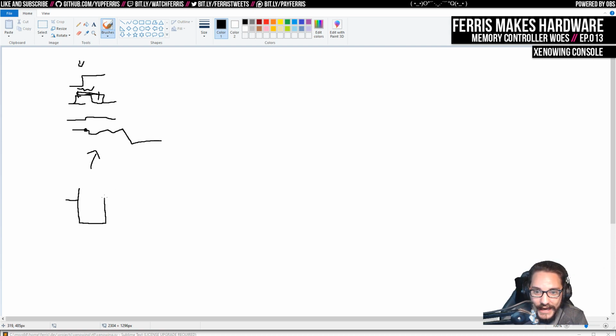The way you do that is, let's say you have your input. In this case, it's a reset, but it could be anything. So I'll just write it in here, and we do a couple of registers. I'm just using this little clock thing here as a symbol for a register. You'll see that a lot. You just have a chain of a couple of these, and then this will be in sync.